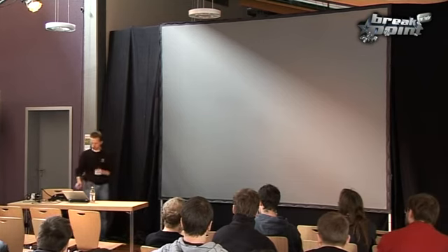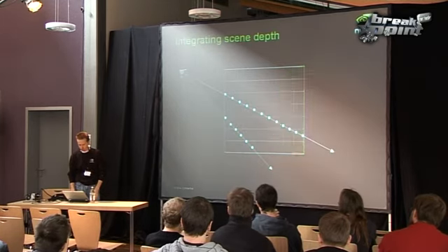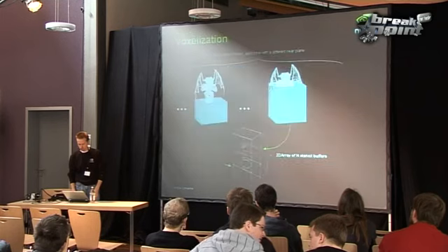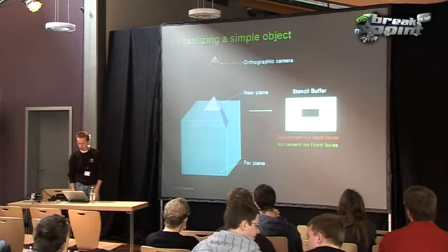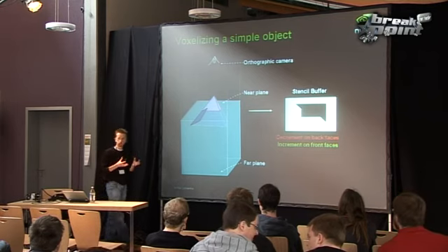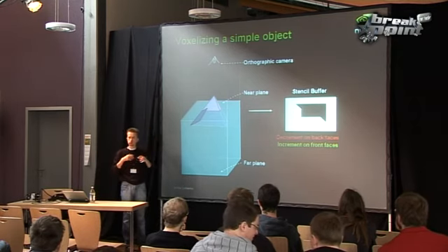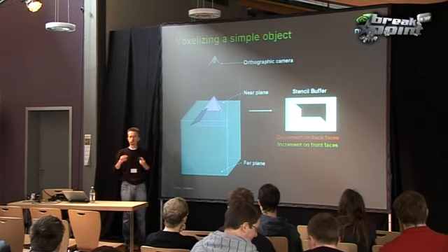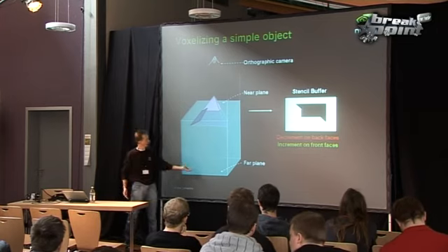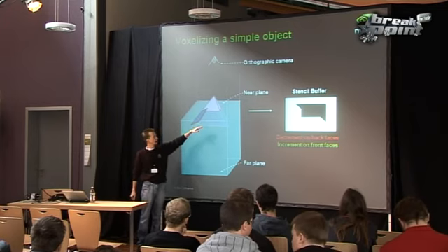I'm not sure that this actually is going to work. So let me go back here. When we do the voxelization, actually voxelization is only possible for well-behaved geometry. The geometry should be closed. It should be a manifold. If it's not a manifold, you'll not be able to determine what's inside. The definition of inside is not well defined for non-manifold geometry. So if you move your far plane towards your near plane, you'll clip off the bottom of the object.